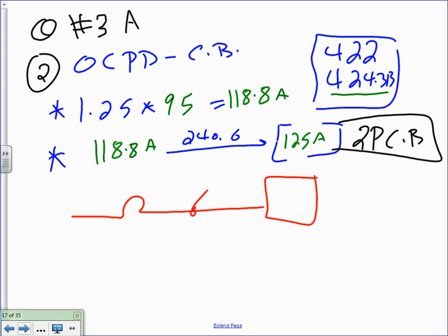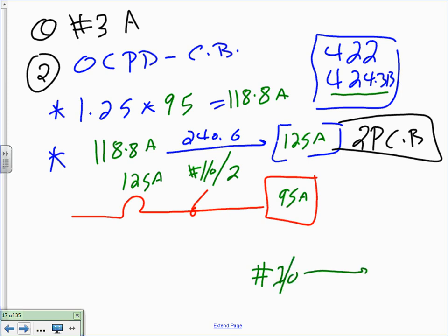This is what you're going to do with your check: 95 amp, 125 amp. What was the conductor size? It's number 1 aught, right? Number 1 aught that we did. So go to 310.15(B)(16), 60-degree column. How much current can that 1 aught give you on the 60-degree column? 125, even? Wow, even.